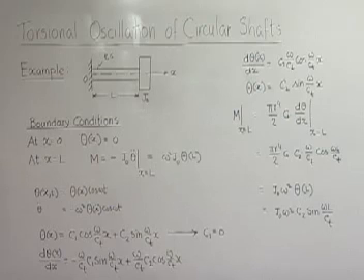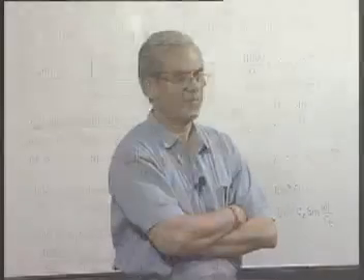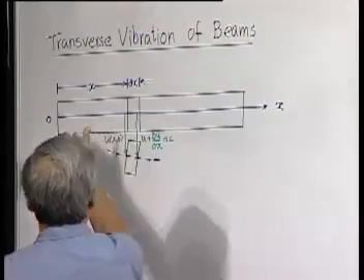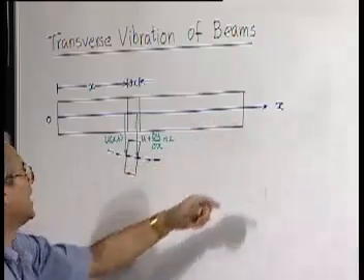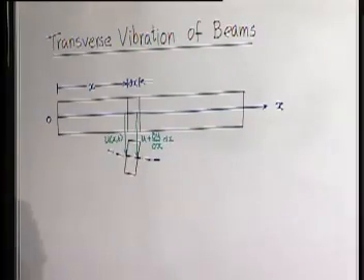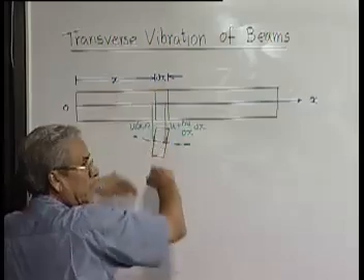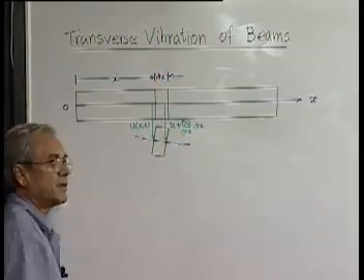It is true that longitudinal vibration of bars, etc. are important, but in reality, most of the time we get lateral vibration of the structural members. So we come now to the transverse vibration of beams and such problems. Again, as mentioned earlier, we will take up uniform beams which are straight, and we represent this beam by this. Its longitudinal axis is x with the origin at one end as before. Now the displacement of the elements will be in the transverse direction.